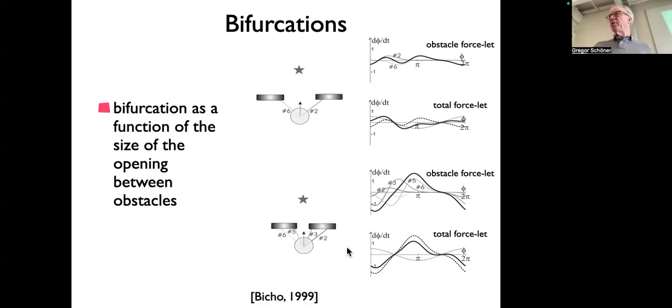And you will see when I show you the simulation, for these things to be right, we have to make these obstacles quite broad, and broad means a broad range over which the contribution is active. In the exercise last week, you checked that once you're outside the range, you are no longer influenced. But if you're still in the range, you're influenced. So if they're pretty broad contributions, then it's not enough to be parallel to the obstacle. You actually have to go a little bit back. And this is where the attractor is pretty much in the back. And you see the robot turns a bit too much, goes a little bit away. It's not so elegant, but that's the price of doing it at this low-level style.